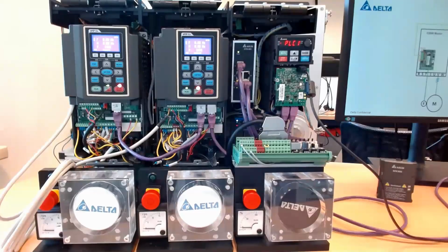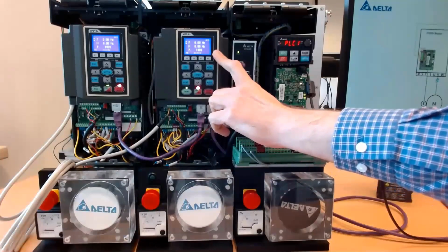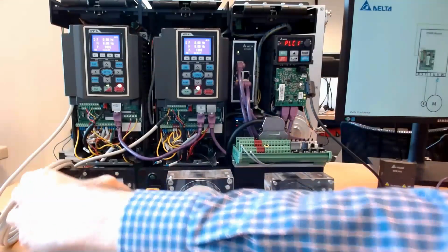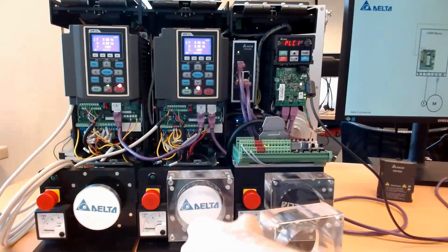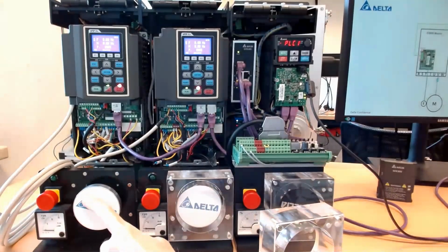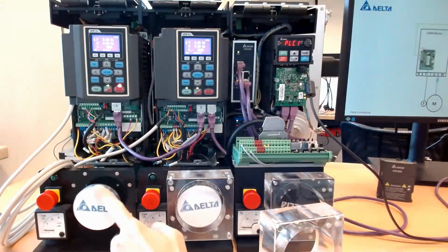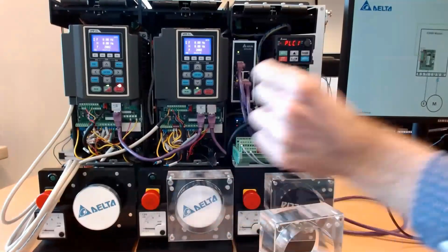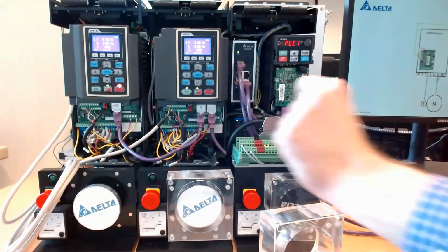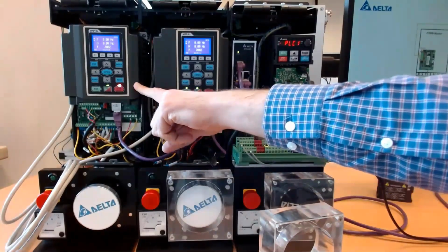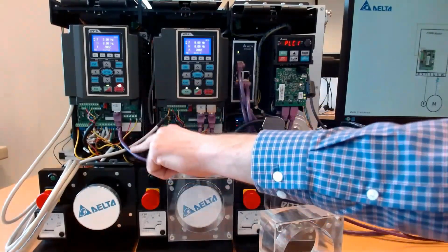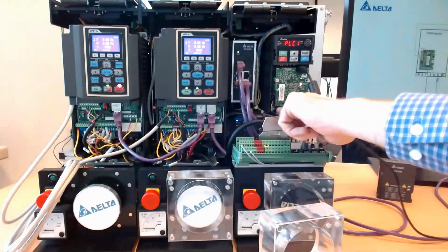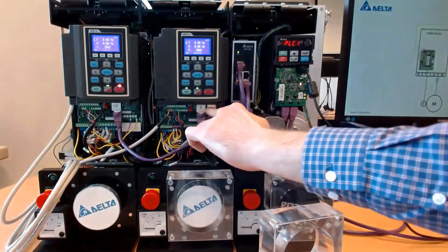Now, I'm not going to go into too much detail regarding the position synchronization because we already have a YouTube video on that. And we also have an application note on that. But yeah, it's very easy to do. So how to do this synchronization, how to program the slave master, I'm not going to show you. What I will show you is how to program this drive in positioning via Ethernet. So I'm going to connect to the AS200 PLC, which is connected here, and then going into a daisy chain all the way here.